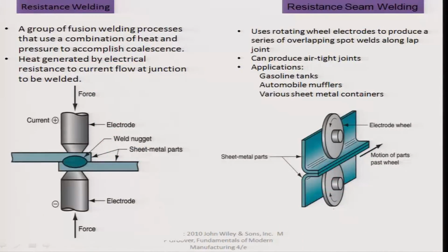We also have some other forms of welding like resistance welding. This is also known as spot welding, which is used in a very major way in all the automotive industries for all sheet joining operations. So here you can see there are two electrodes which have a high current between them, as well as pressure. So there is a solid state welding as well as some kind of nugget formation at the sheet to sheet interface, where there is joining by virtue of a fusion welding process at the interface between the sheets.